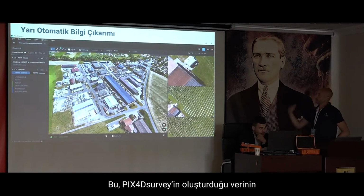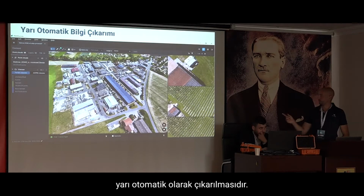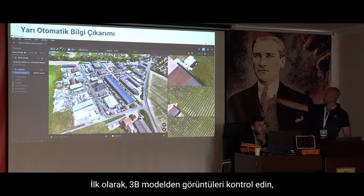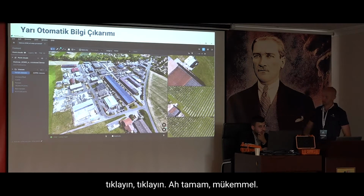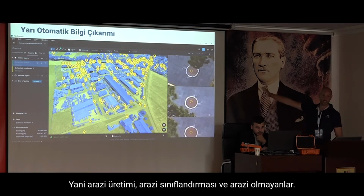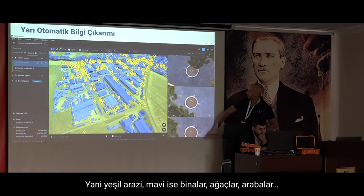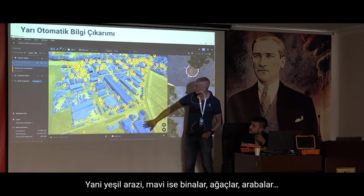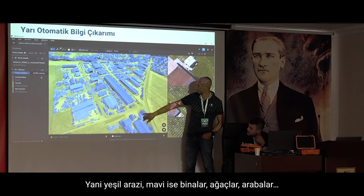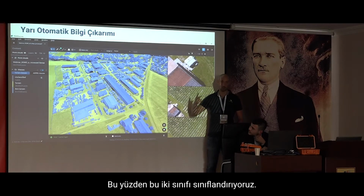This is the semi-automated extraction of information in PIX4D server creating. First, starting from the 3D model, checking the images. Okay, perfect. So the terrain generation, classification of terrain and non-terrain. So the green is the terrain, the blue is buildings, trees, cars, everything that is not terrain. So we classify these two classes.